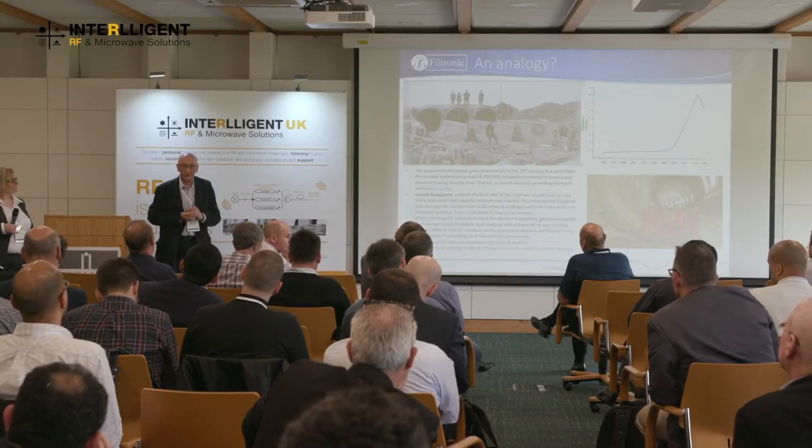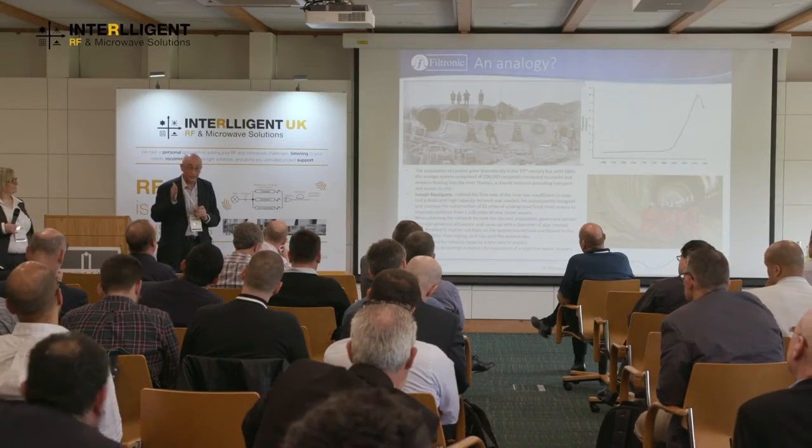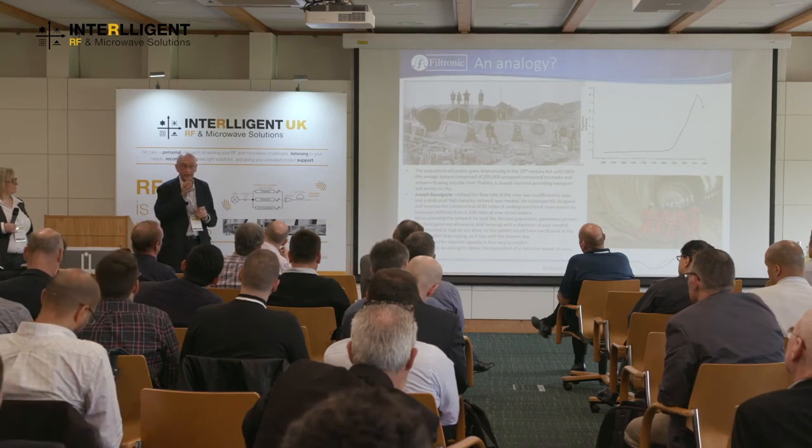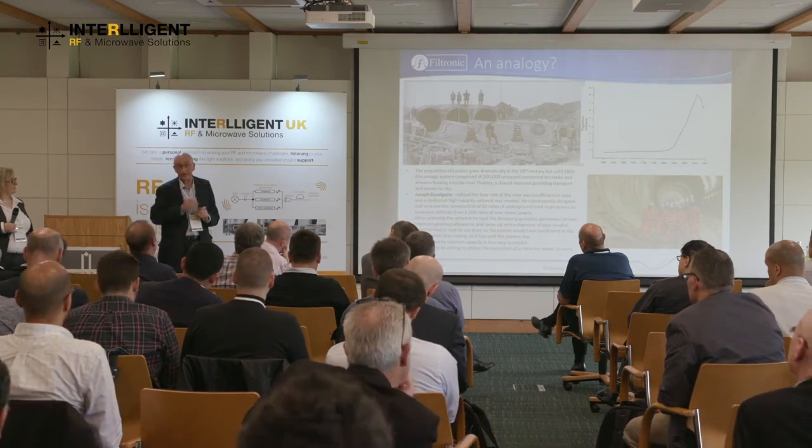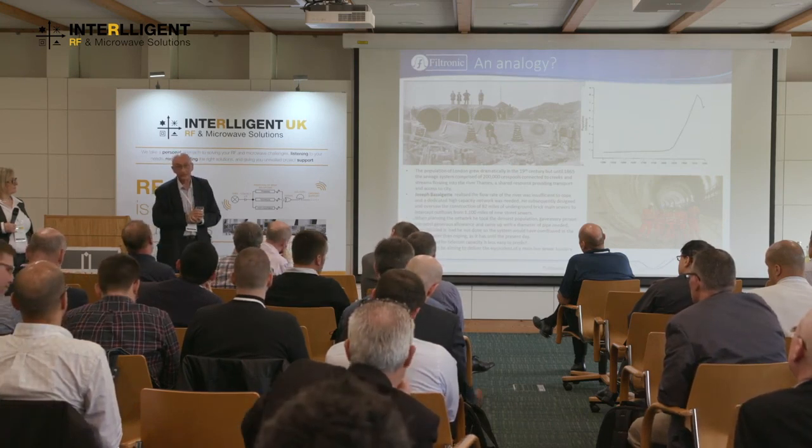The FCC have got a different set of rules to ETSI. At ETSI, you need a minimum antenna gain of 30 dBi, I think it is, which can be quite difficult for a sectorized or a switchable antenna. They tend to be quite low gain, probably 17 or 18 dBi. So I can see those things working at perhaps up to 60 gigahertz. I'm not sure about at E-band. I think that might be pushing it a little bit.